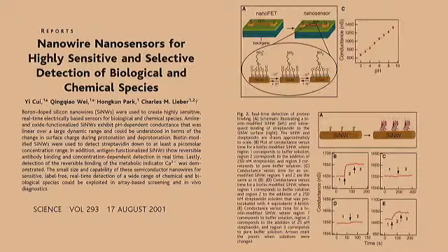Analyte basically adsorbing on the nanowire can cause electron doping or electron removal, whatever it may be, and therefore cause a change in transport or the resistance through the nanowires, right? Metal nanowires, you do not expect this to happen. To put it very simply, metals have tons of electrons, right? And therefore, addition of a little bit of electron or removal of a small amount of electrons is not going to change anything much. So you do not expect a metal nanowire to exhibit this behavior, okay?